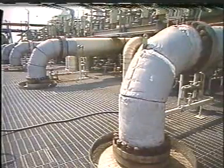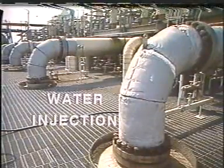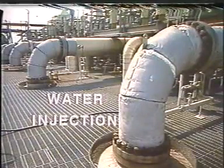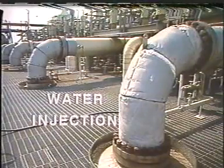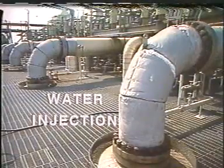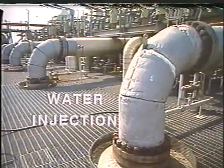A small amount of water is sometimes injected into the feed or recycled gas streams to spread the chlorides across the catalyst. Water injection rates must be carefully monitored to ensure that the chlorides are properly dispersed. Chlorides and water are often injected at the same time to keep these two variables in balance.